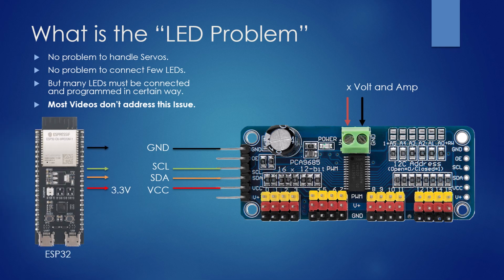Then we connect the signal to the microcontroller. Here we're using an ESP32. The 3.3 volt output connecting to the VCC should not have more load than about 150 to 200 milliamp. ESP32 also has a 5 volt output. Do not connect to that output, because the I2C bus pull-up resistors on the PCA9685 would be using 5 volt back to the ESP32, and that would be no good.